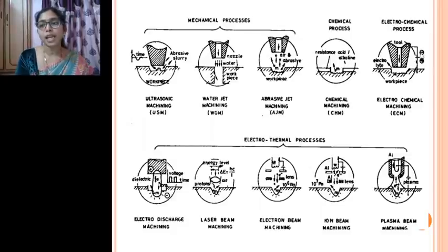And next we have seen the electrochemical process, which is the same as the electrolysis process, where a tool and a workpiece electrode will be placed. Now in this process, if instead of a tool of a cylindrical or any particular shape, you replace the tool with a grinding wheel, then it is called the electrochemical grinding process, where the wheel will be rotating.